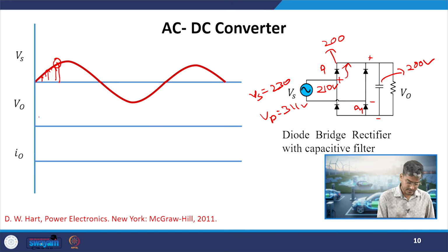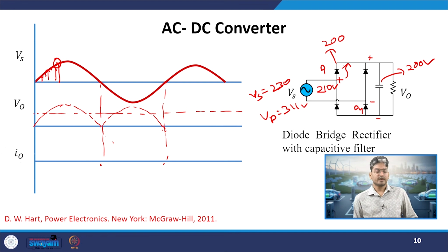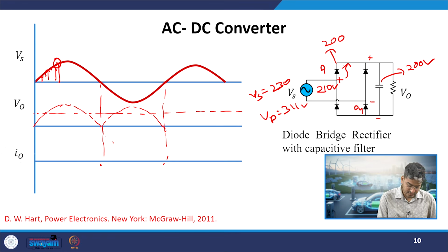Suppose this is my capacitor voltage. So, where can it conduct? In the previous case, this was our waveform. Now, at what stage can it conduct? Only when my input voltage crosses this capacitor charge voltage. So, it will be conducting for this duration. Again, your capacitor voltage will not be a straight line; it will be slightly sloped because the capacitor will be discharging during this time. So, let us remodel this one. It will be a bit discharging, with a drop in slope.